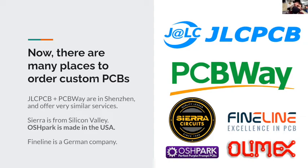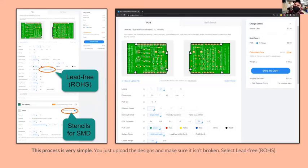So essentially all you do is upload a Gerber file and you get all of these different options. I always choose lead-free solder. It feels like a worthwhile upgrade to me, which is RoHS, restriction of hazardous substances. And then if you want, you can get a stencil for SMD soldering. If you're going to SMD solder, it can be fun to do this every once in a while. It helps lay down the solder paste just fine. So if you're getting there, a stencil is a neat add-on for about $8. It's a sheet of metal that helps you lay the solder paste down in just the right spots.